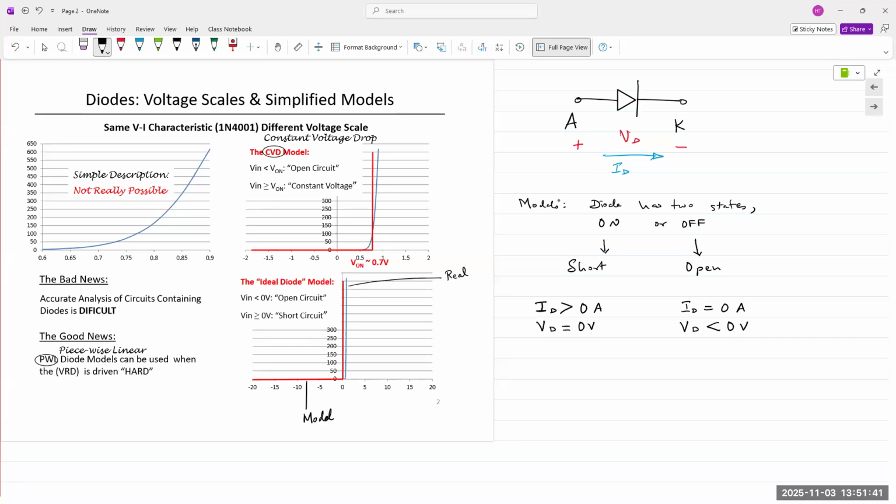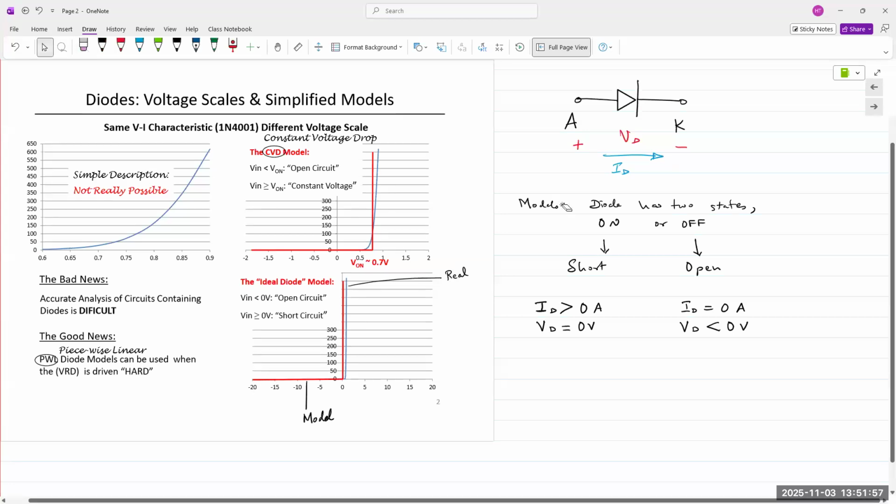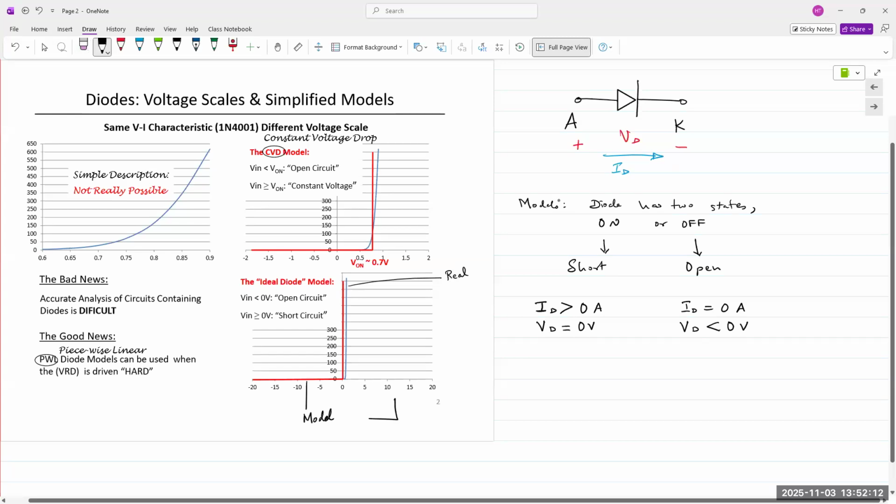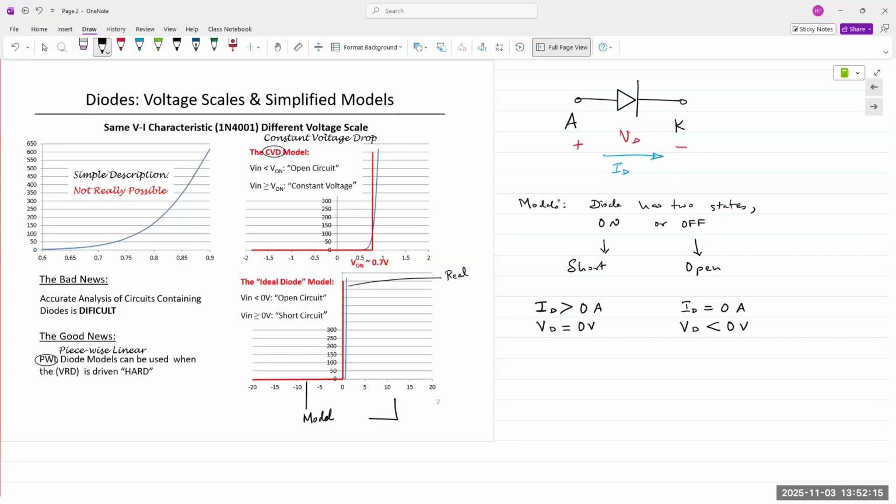And what it says is, if the voltage that is applied to the diode is less than 0 volts, meaning negative, then the diode voltage is negative and the current stays at 0. And when it turns on, diode voltage is at 0 volts, whereas current increases because it's allowed a pathway to flow through. Hence the characteristic is simply a corner turn like that. And that is based at 0 volts. Does that make sense?